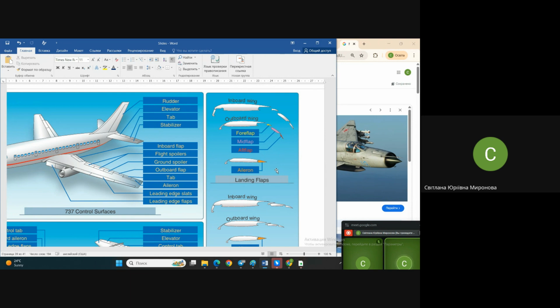Like yesterday, I gave you an example with an airplane, assessing necessary takeoff weight and necessary thrust during horizontal flight due to airplane quality, predictable airplane quality, the ratio of lift and drag coefficients, and 100 passengers for a middle distance airplane. 100 passengers means 12 tons of payload, because passenger plus luggage is a standard value, and this 20 tons is around one quarter or one fifth even of payload.